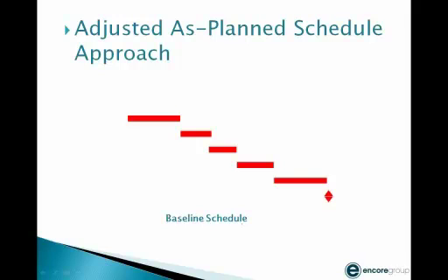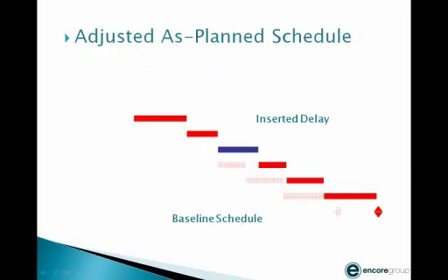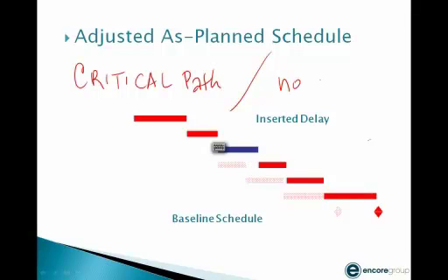It's pretty simple. You have a baseline schedule. Here's a critical path. You plug a delay into that critical path, and it pushes the end date out. And you say, okay, we want this much extra time. The only problem, well, there's a benefit to this analysis, and then there is a negative aspect of this analysis. The benefit of this analysis is you have a critical path. Because you have a critical path, you can actually analyze it and say, here is the delay on the job, and it has impacted our critical path. The downside of it is, the negative side of it is, there's no as-built information.